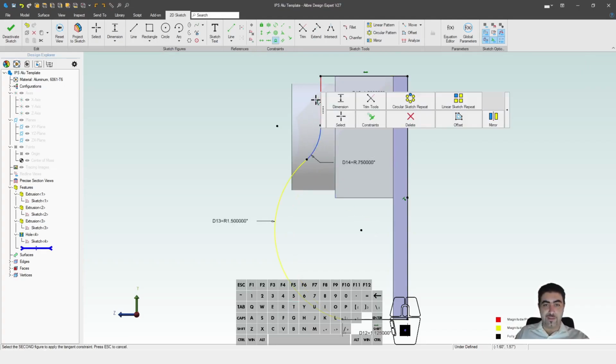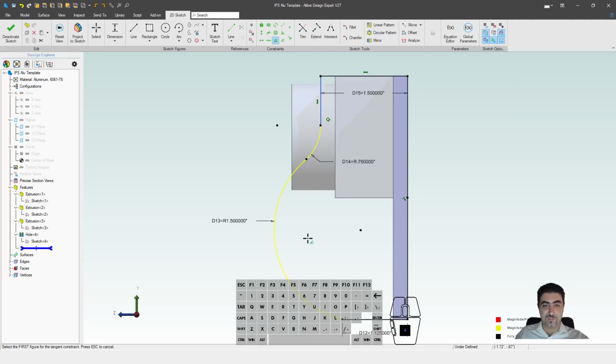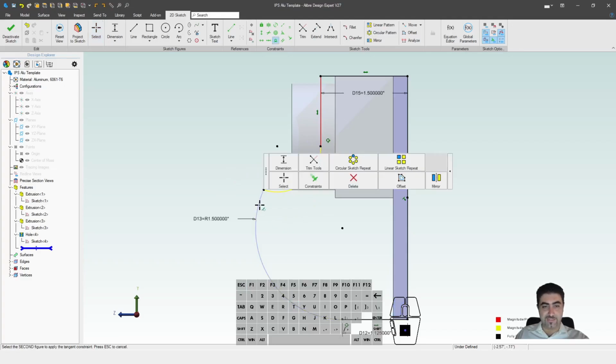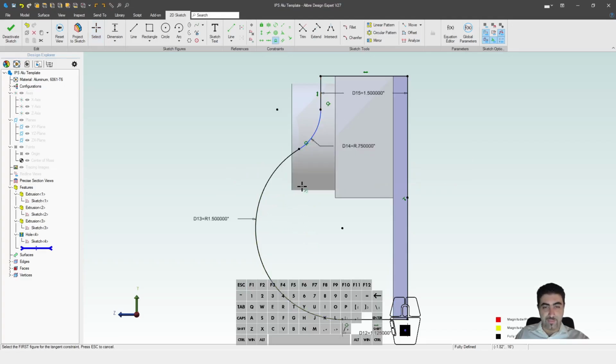Okay. I go ahead and put my tangents. The order was very specific, right? And you will see me adjusting this. It's to make sure that this side doesn't throw it off, right? And then as soon as I see that this got registered, hit C immediately, go for the center point, move the mouse a tiny little bit, just enough to get that. 0.5, enter. My sketch is done, so what do I do now?